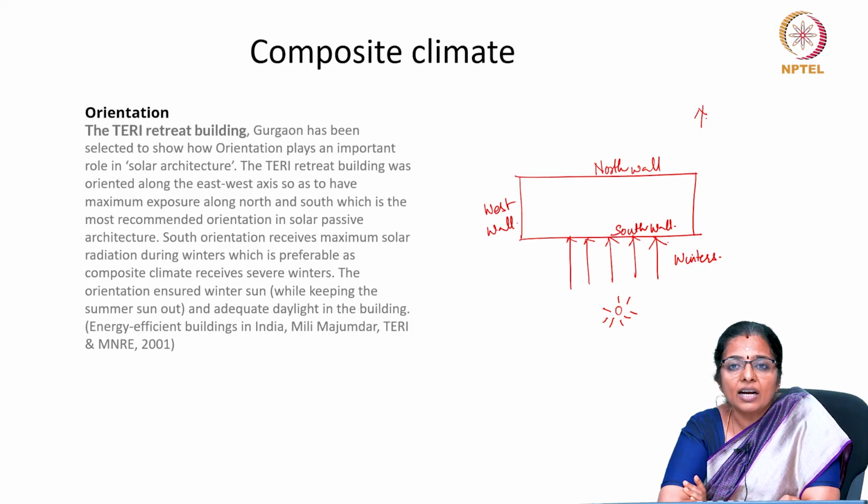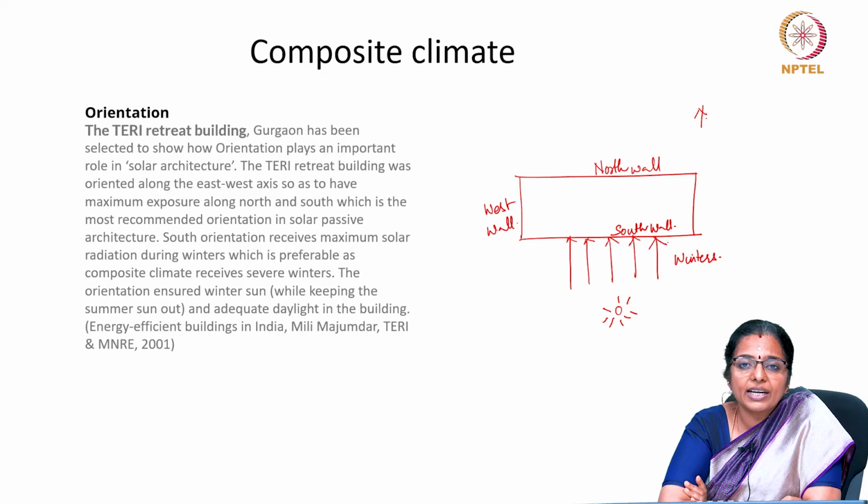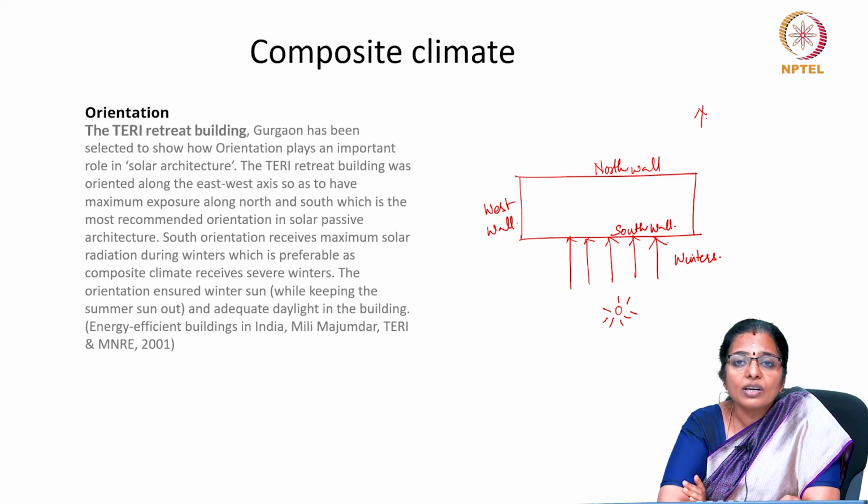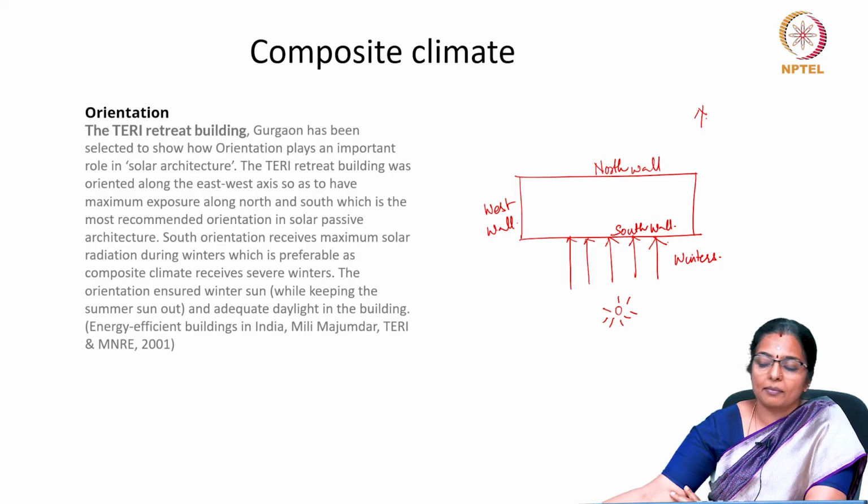These buildings are of rectangular form, as this is the ideal orientation with their longer axis towards the north-south direction. Greater the perimeter to area ratio, greater is the heat gain in the building, unless you are making an attempt to bring in the heat from outside to inside through certain surfaces.